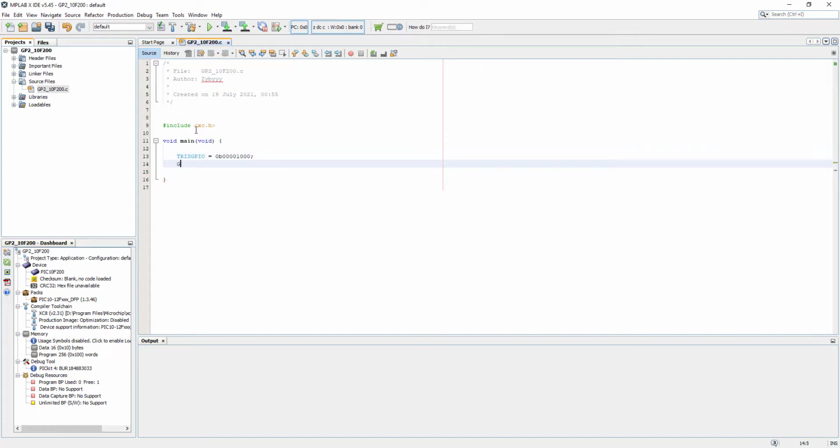Now let's go and program our 3 bits that we can use as an output. So in here we're gonna say again in binary the 4 of them 0, the 4 of the top ones, they're not there basically. Okay, and the 4 lower ones, we know that the GP3, which is the 4th bit, can be only input, so I'm gonna leave it as 0. All the other 3 ones I'm gonna set to the high state, so I'm expecting to be around 5 volts there.